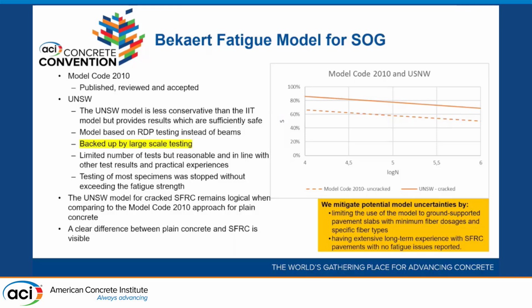This is a complicated topic. There's not a lot of data out there. There's data showing that fibers do help concrete perform better under fatigue, but there's been no real practical application for them for slabs on ground. So we say, okay, it's complicated. This is kind of new. There's not a whole lot of information out there. So that's why we're going to limit to just simply ground-supported pavement slabs. There's a minimum dosage that has to be used in the slab no matter what.